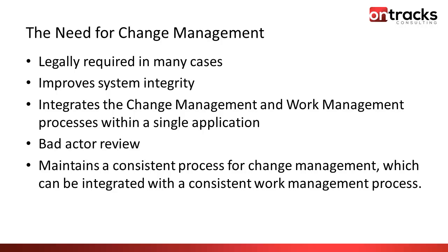So why do people need management of change? Management of change is actually legally required in many industries or for certain assets. For example, in Alberta, there are regulations requiring that change management processes are used for any changes to pressure vessels, and that's dictated by ABSA rules. There are various rules and regulations dictating that change management is required for various industries. It's also beneficial because it improves system integrity by making sure that everything is properly tracked and managed.